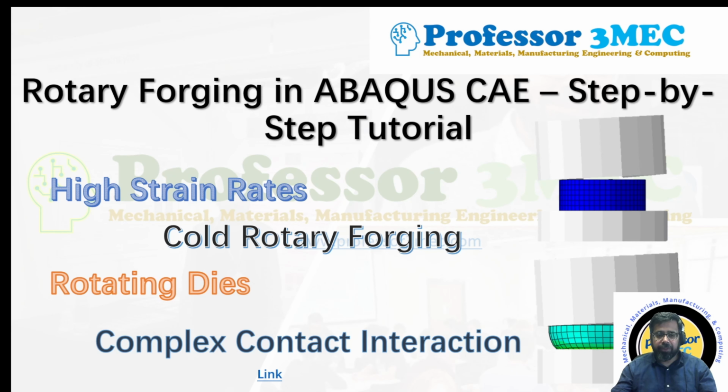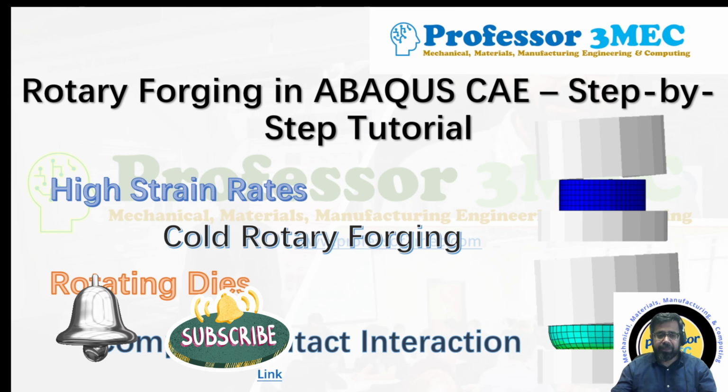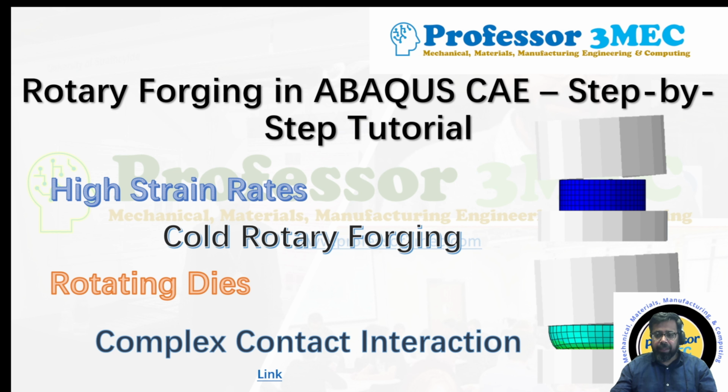Today we are going to learn about rotary forging and its simulation in ABAQUS CAE, and I will give you a step-by-step tutorial on that. As you can see on the slide on the screen, it's a high strain rate problem. We will be focusing on cold rotary forging. The dies will be rotating and impacting at a very high velocity, and also, as you can imagine, it's a complex contact interaction which we have to define and solve.